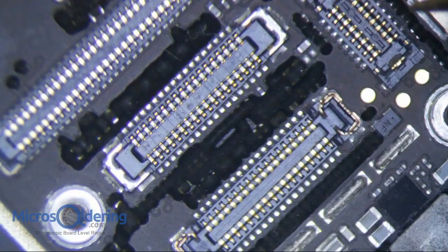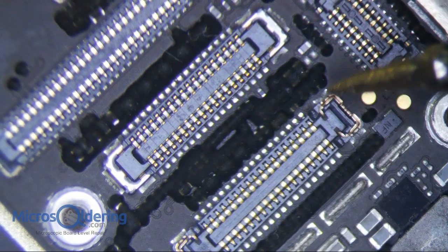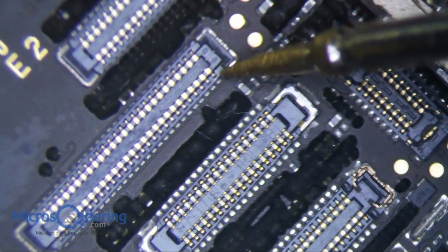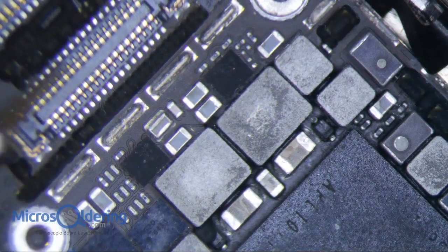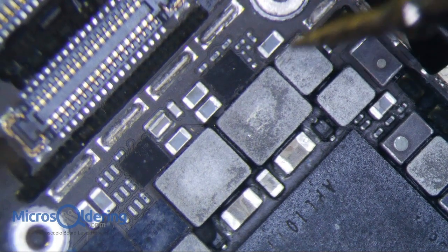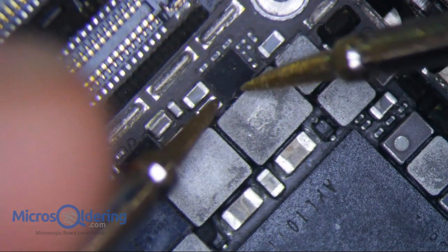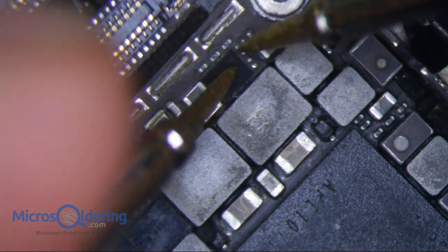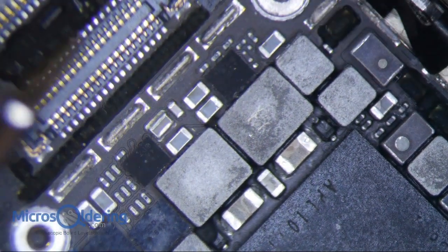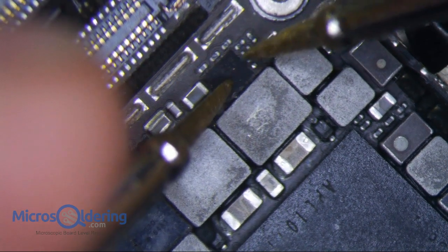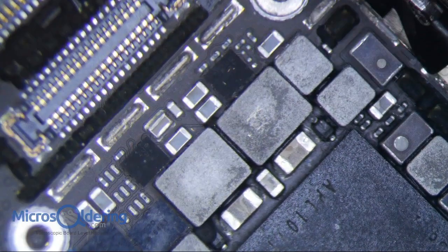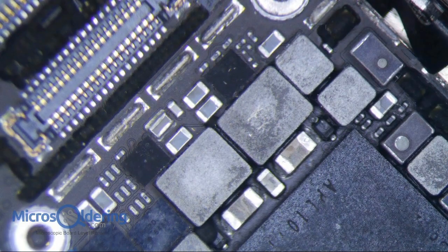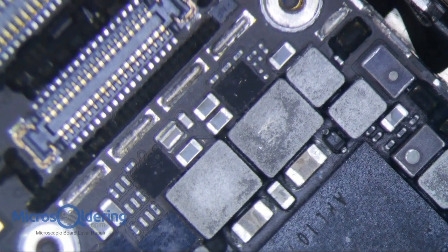So why are we still not getting 17 volts at this connector right here? I'm going to assume that it is probably the backlight IC because everything else looks pretty clean. I have run this through the ultrasonic cleaner already, and there was noticeable gunk around here. It was water damage. I imagine that something got corroded below the chip, so that's what we're going to do. We're going to replace the chip and see if that fixes the problem.